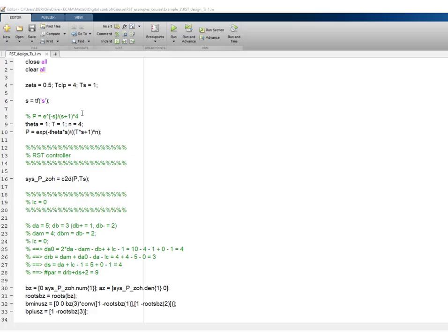So this is the Matlab code for this second example. This is the process. We have introduced the Matlab variable and the following parameters, so you're really working on this process over here, and these are the specifications. The sampling time is 1 second. So as usual, you need to obtain the zero order hold equivalent discrete description.